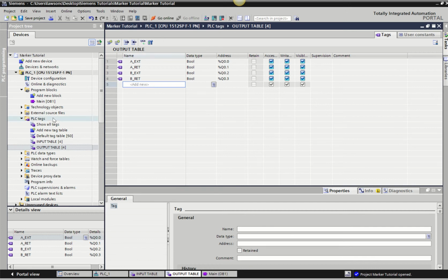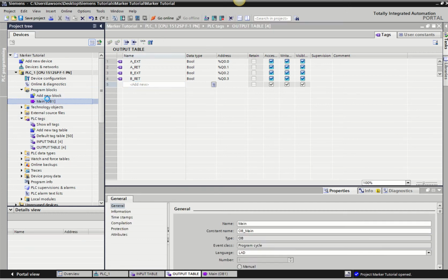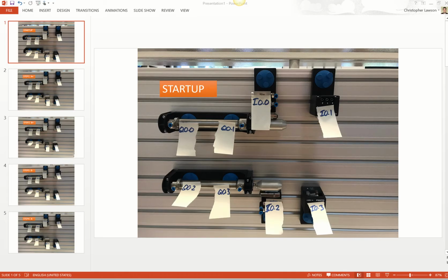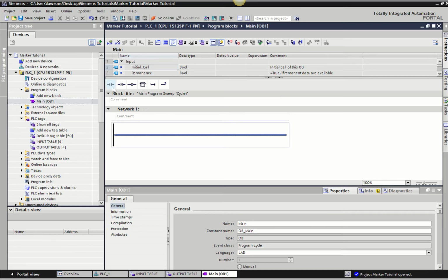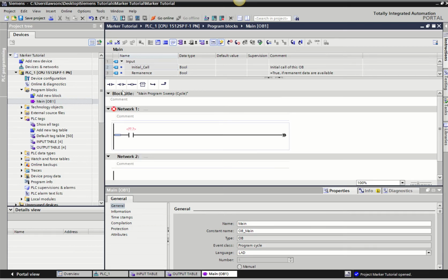If we look at this in a very basic sense, we go into our code. Our starting position is this here, both cylinders fully retracted, and two inputs are going to be activated. We're assuming these are normally open inputs, and those two inputs being activated allows us to start our sequence. So we can easily add in our two inputs, which are when A is at its minimum and when B is at its minimum.